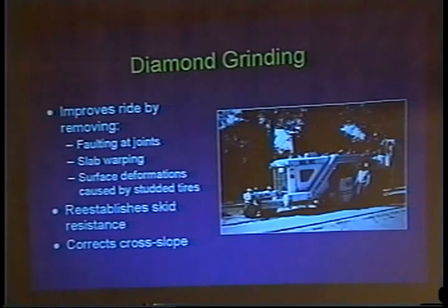Diamond grinding process: a typical machine like that, a heavy machine, bears down onto the concrete pavement, and pressure is applied onto this cutting head, which is a drum of diamond saw blades placed in close proximity to each other, probably about a 3, possibly a 4 foot length of drum, with multiple cutting heads in through there.